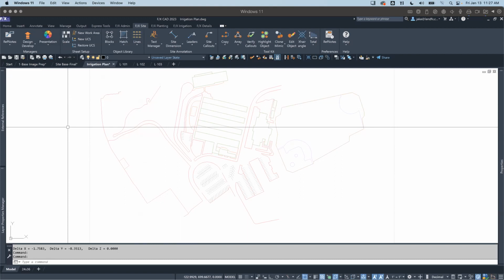Okay, so here's where actual scale comes into play, and how we need to start to lay out our sheets in order to know what scale would best fit. Now, I know I might ruffle a few feathers here, and I understand that there's a lot of different regulations and restrictions to what scale you have to abide by on certain projects. I get that there's conditions for all of this, but for the most part, a landscape or an irrigation plan and our symbols are geared around a 1 inch equals 20 foot layout.